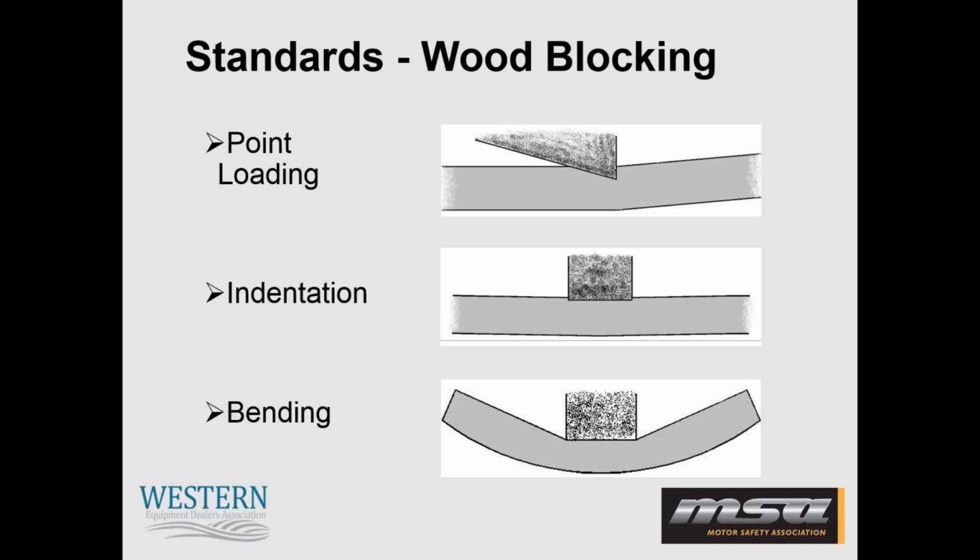And the moisture content of the wood blocking plays a major role in how a block carries a load. For example, if you have wood blocking with normal moisture content, the wood blocking will slowly crush and make the odd creaking sound, which is what you are looking for when it comes to blocking.